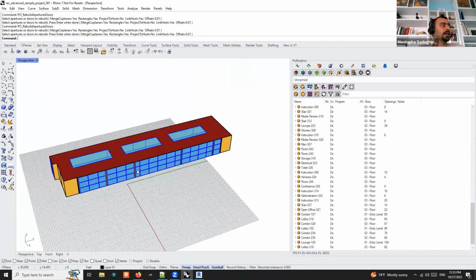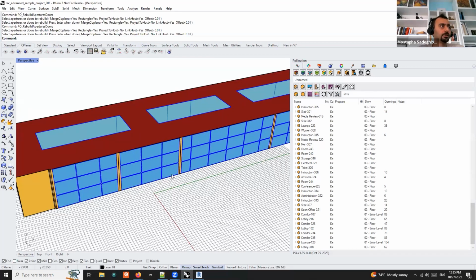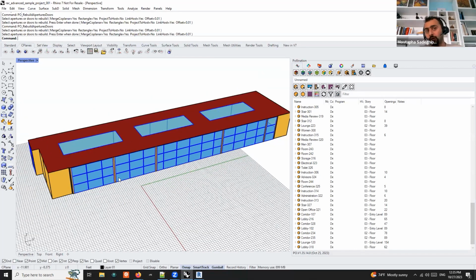So that's a judgment call to be made. For me, this is one of those things that I would just go and fix in Rhino. But if you don't want to use Rhino, you can spend the time and edit it. This is one of those cases where the architectural model is not necessarily inaccurate, it just modeled the way that it looks correct in the documents. But when you want to create an energy model for these skylights, you will have this issue. Any questions? No.